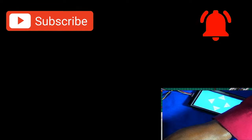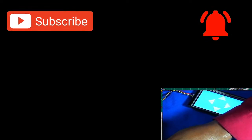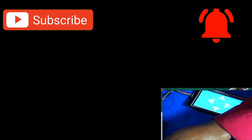So I'm not going to bore you with a lot of explanations. I'll just show you what I think I needed to do, because the message was consistent. It keeps saying that my Nextion was not declared in this scope, and really I don't see that I declared it. Right, I know I have it in the void setup, but that was it. I didn't declare it. So for my Nextion, I didn't give it a name. So I think that was it. So I have to fix that. So let me just show you what I mean by that.